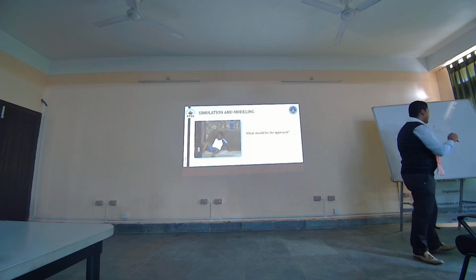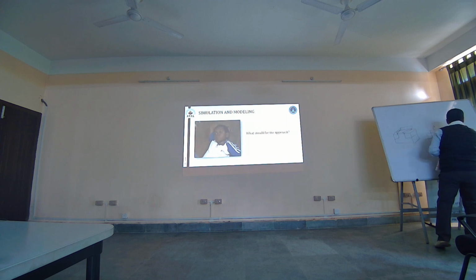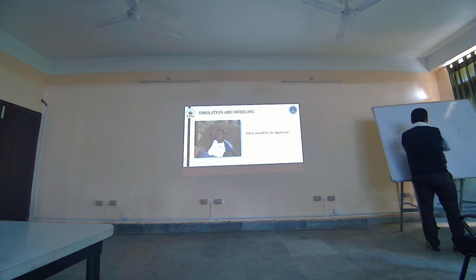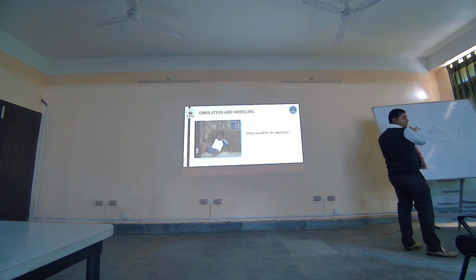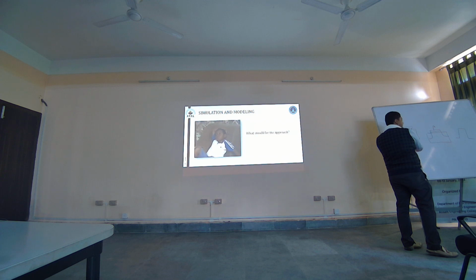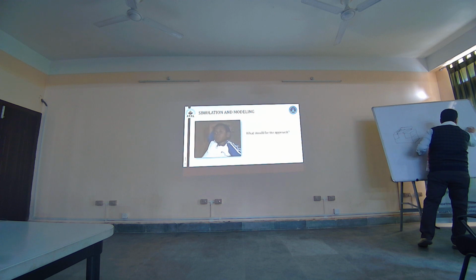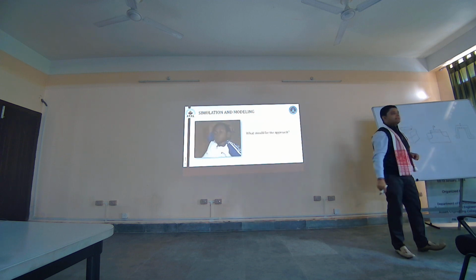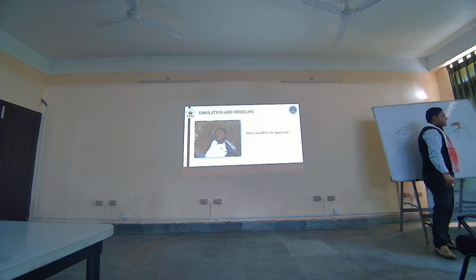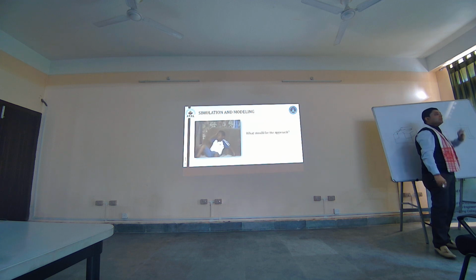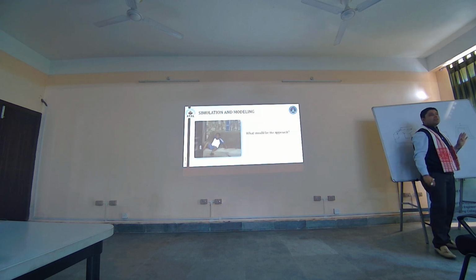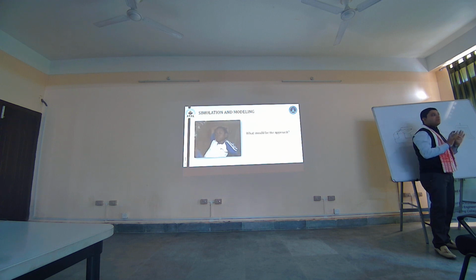The only difference is that they have a kind of fin structure, whereas here your body is simply a straightforward thing, and you have just a planar structure on top of this entire channel. But in case of FinFET, the gate will wrap around the entire device. So the gate oxide and your gate will have control from all three sides, or sometimes from two sides depending on the thickness of the fin. But basically you are going to increase your electrostatic control over your channel. So that is the basic concept of FinFET.